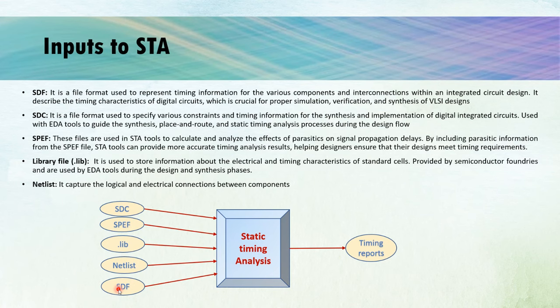The next input to static timing analysis is a library file, or a .lib file. This .lib is a library file that contains the information about the standard cell libraries used in our digital circuit design. It is a crucial component in the process of designing and optimizing integrated circuits. As the name suggests, the term library basically refers to the collection of predefined, pre-designed, and pre-characterized digital logic cells, each of which performs a specific function. Such as NAND gate, AND gate, flip-flop, OR gate, all those gates' information is stored in these library files.